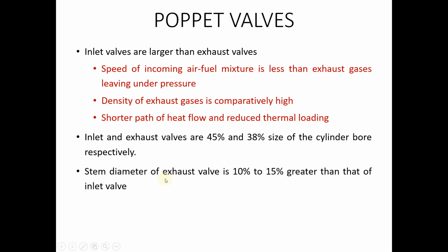The stem diameter does not actually affect the cooling process, because, as you can see in the coming slides, the highest temperature is experienced at the valve head, and as we move along the valve from the valve head to the tip, the temperature decreases. So the temperature at the valve head is larger when compared with the valve stem. So even if we increase the material in the valve stem, it does not greatly affect the cooling process.